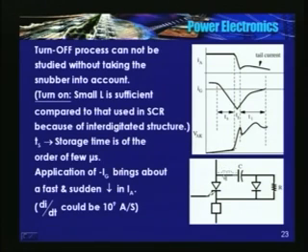If this inductance were 0 and turn on time very small, then maybe immediately this anode current finds a path to the capacitor. Now because of this inductor and diode, this current gets choked, and therefore a large di by dt spike appears across the GTO. It could be dangerous, in the sense that the device may fail because of this spike.